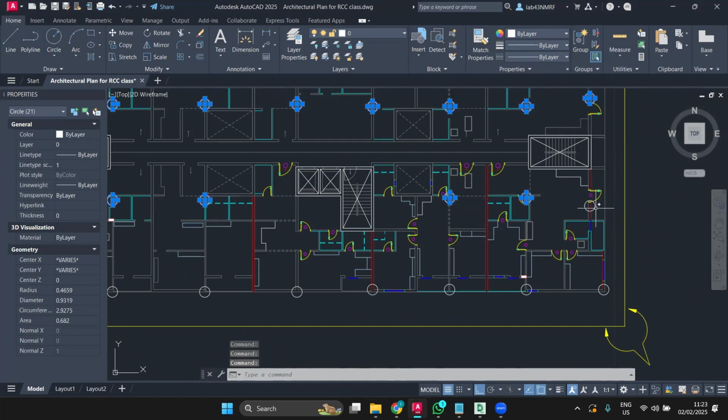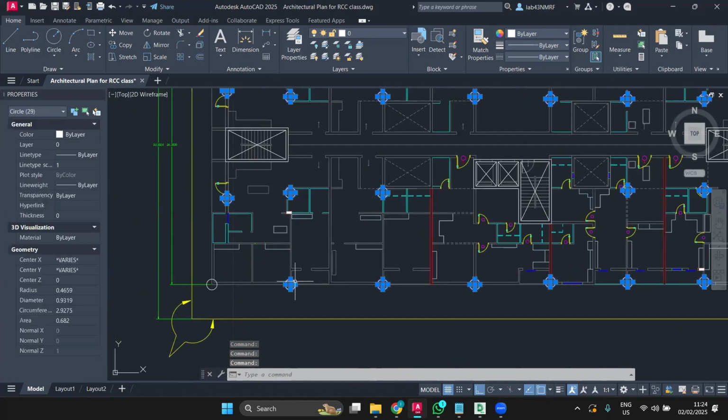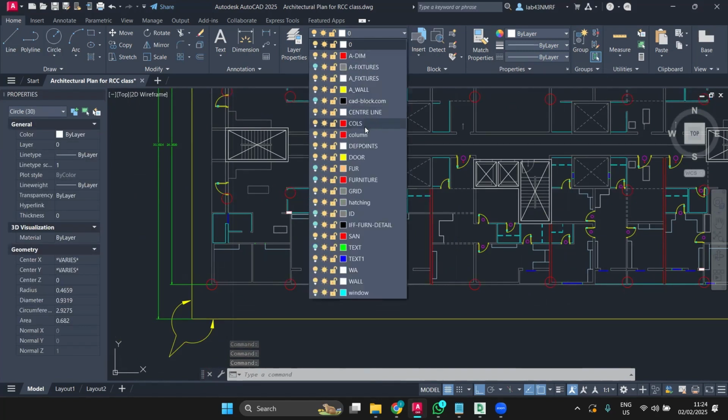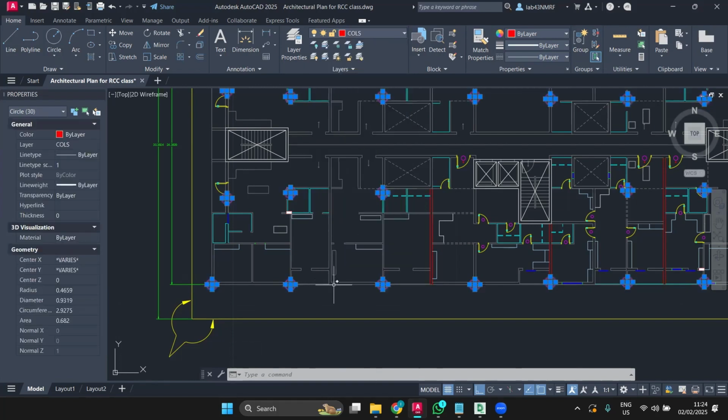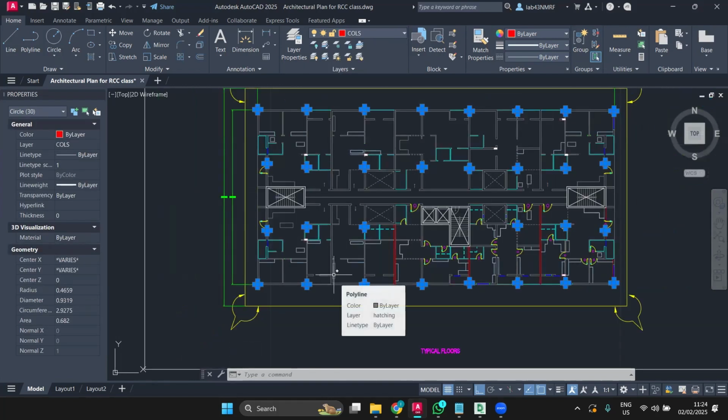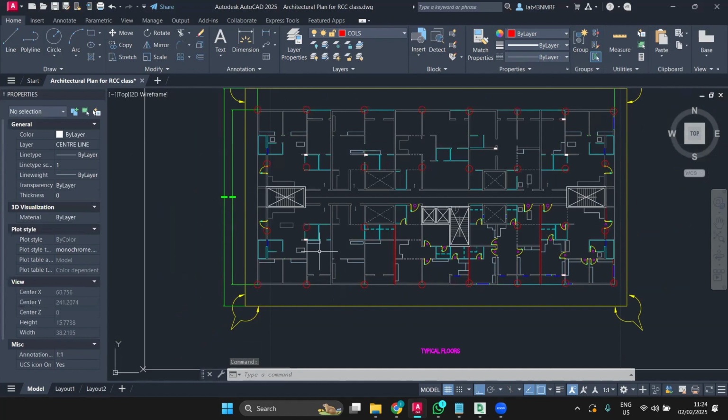It's easy actually. When we give you the architectural drawing, within half an hour we'll place the columns and give it to you. The moment we place the columns, 95% you will never change them afterwards, because we are going systematically. We take the architectural drawing, place the columns at a bay of 8.5 meters, place the core wall and staircase, and calculate the column sizes with respect to the ACI code. So 95% will never change afterwards once placed. Maybe 1 or 2 columns here and there will have a minor difference. You understand what I'm trying to say?